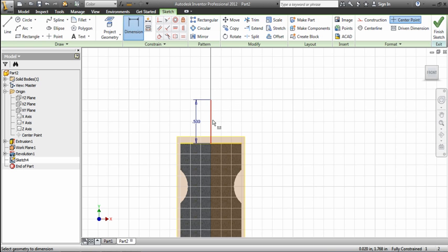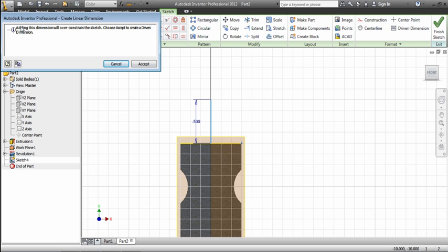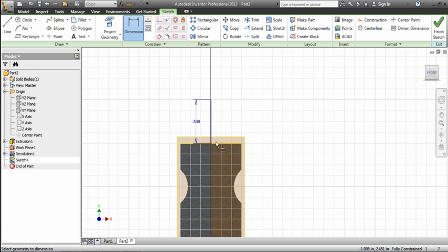and I'm going to dimension this line to the edge here, I can't change this. It said adding this dimension will over-constrain the sketch. Okay? Because I've locked this line onto the middle, it cannot move from back to forth. But if I were to make a line somewhere along the line that wasn't locked onto the middle, now I can dimension this from one side to the other. Don't worry about making this line. I just wanted to kind of go over that really quick. Okay, I'm going to delete this.